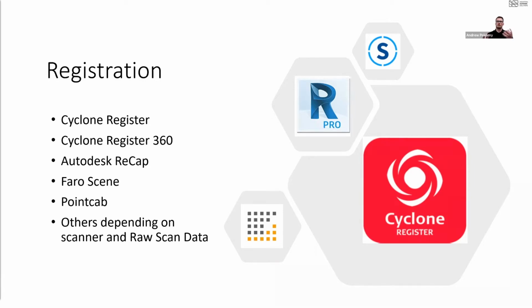Because each of those individual scan locations, all it knows is what's that distance, what's that angle, what's that intensity, and we've got to take all that information and turn it from a bunch of individual items into a complete picture of the site that we scanned, and then make sure we do quality control checks on it to verify that everything's aligning correctly, and then we lock it down and georeference it to the coordinate system that we had out there.